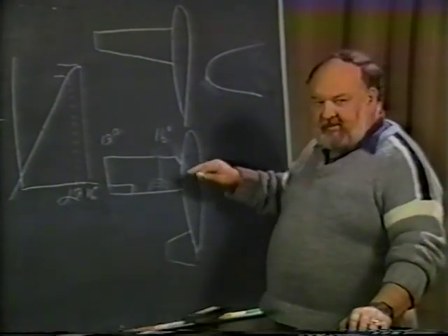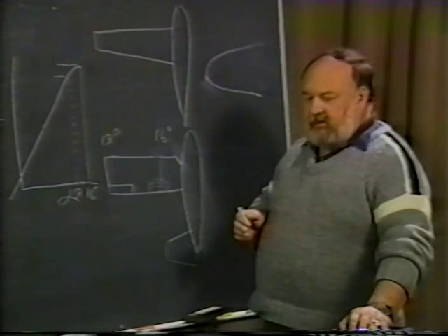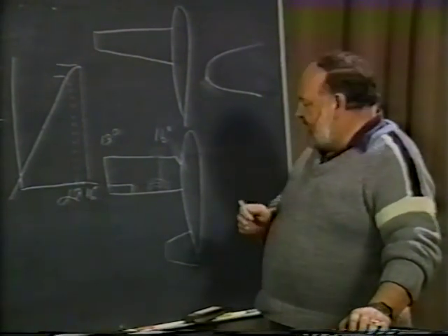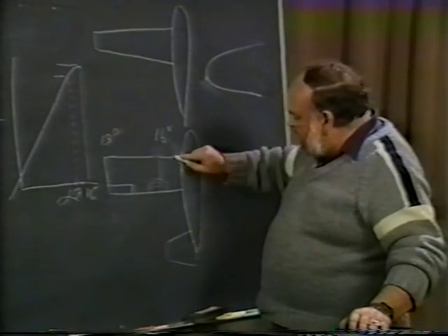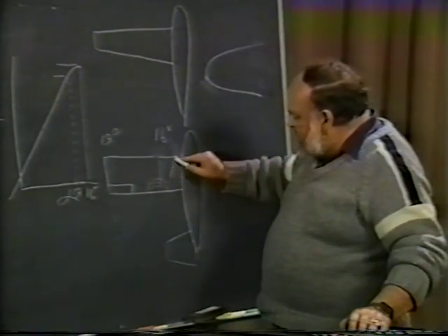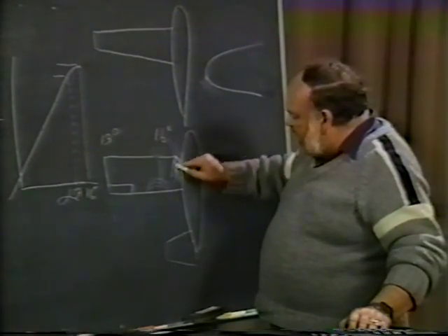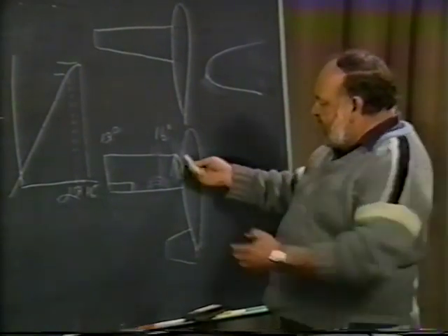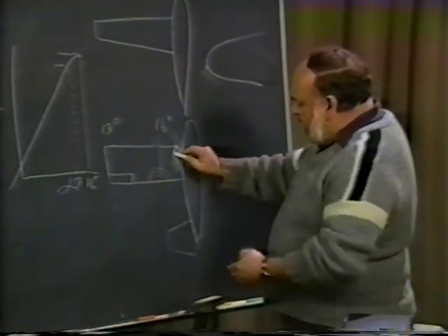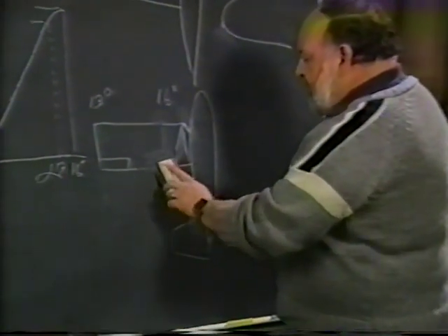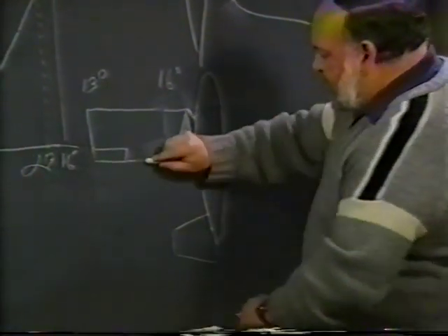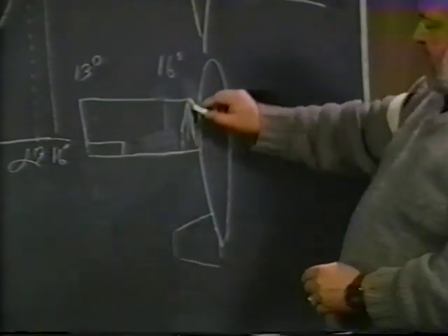His windshield now is at a much lower slope angle, less drag on that, good visibility with it. But one of the key features that happens is that this sharp edge here causes a flow vortex to build up as the air comes around the leading edge and it gets the sweep back, it rolls around, and this region in here is the region that will tend to stall. So he ends up with a real nice stall pattern, forcing it right inboard here.